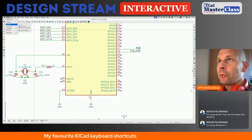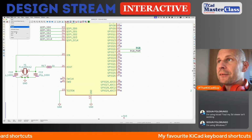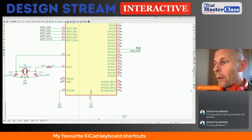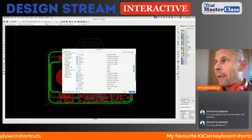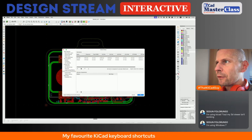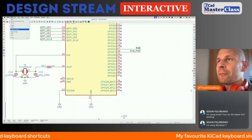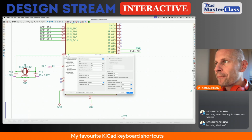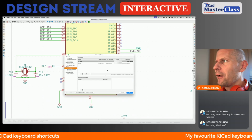And now I will show you where to add the net classes. The first, older way is from the PCB editor. Go to board setup, and here are net classes, and add a new one. Simple as that. But I think for some time you can do that even in the schematic editor. So go to schematic setup. Here is net classes, and basically the same dialog.